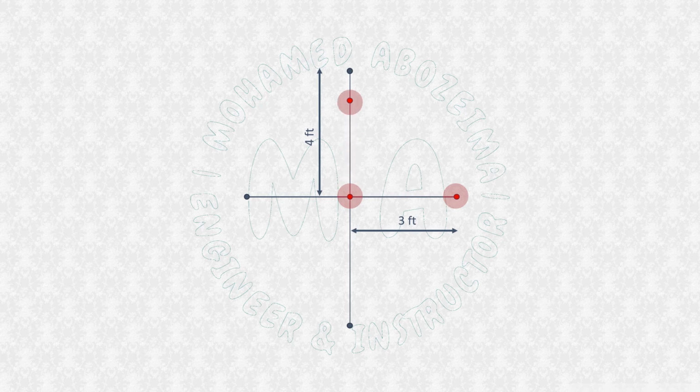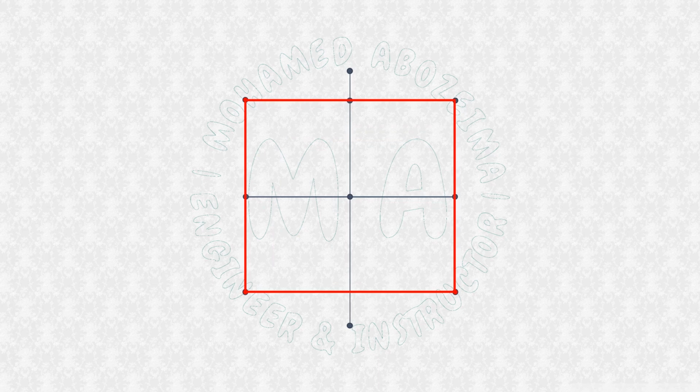Go to the next point. You should read 6 feet on the meter. Move the meter till you can read 9 feet, which is the sum of 3 plus 3 plus 3. Then drive a steel bar. We finished the first rectangle. Repeat the process 3 more times to complete the cellar area. Well, we should have increased the dimensions of the cellar to accommodate for the cemented area. We can use the same method to complete the subbase area.